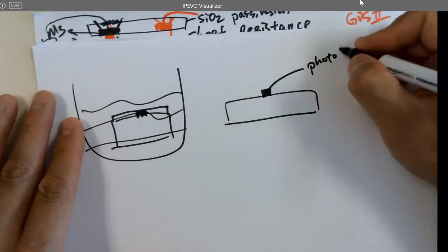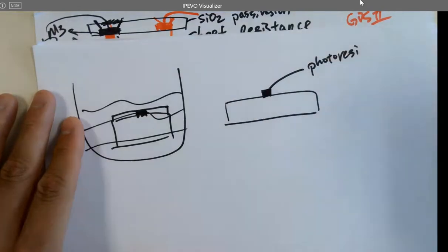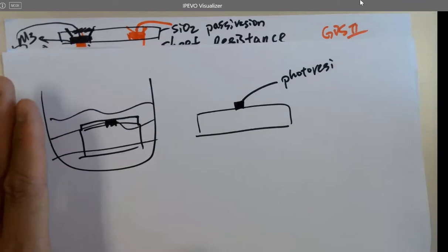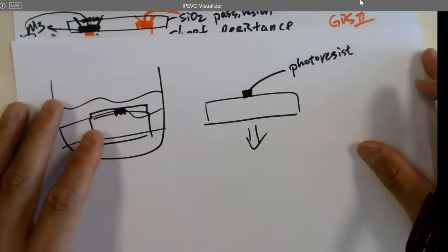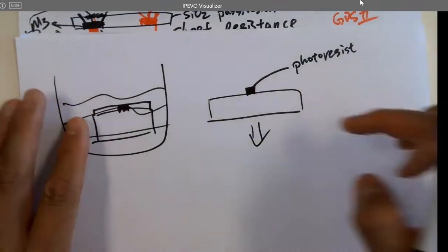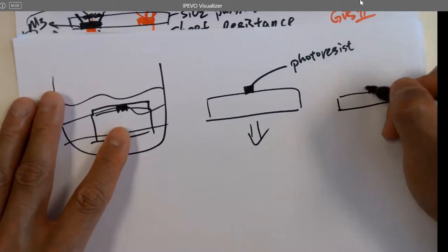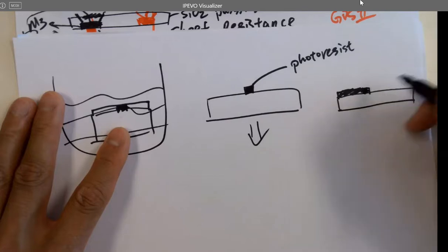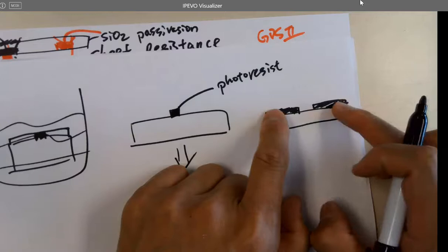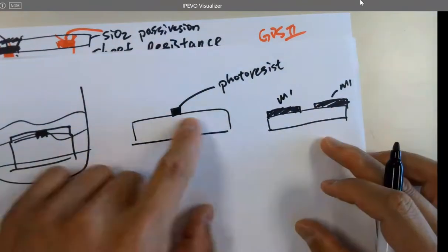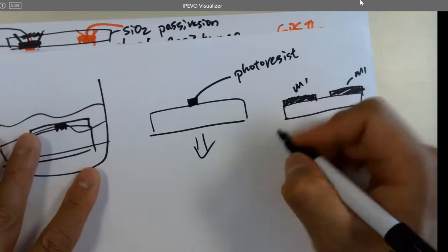Do you need a photoresist for a chip, for the final product? Yeah, it's something blocking the dopants, sometimes it can be a metal, not the dopant, but metal, right? And then what's next? What you can do depends on the purpose, right? For example, the final goal of this process is to fabricate two metal wires here and here, but not here. That's the goal of it. That's the circuit. That's metal one. How to put metal on the wafer? It's called deposition.